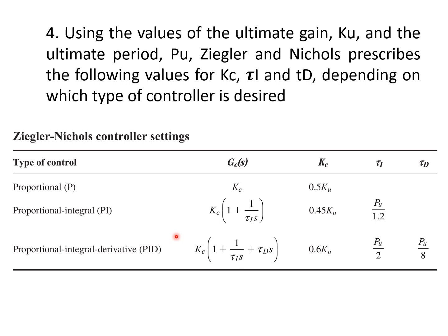Okay, and as I said, you may have done it in your lab. You could have seen this. In your lab you may be dealing with proportional band instead of KU. It's just the inverse: KC equals 100 over proportional band. It's just an inverse of the formulas, but the methodology is still the same. So you can get your tuning constants using Ziegler-Nichols, and this is based on experimentation done by Ziegler-Nichols to come up with tuning.